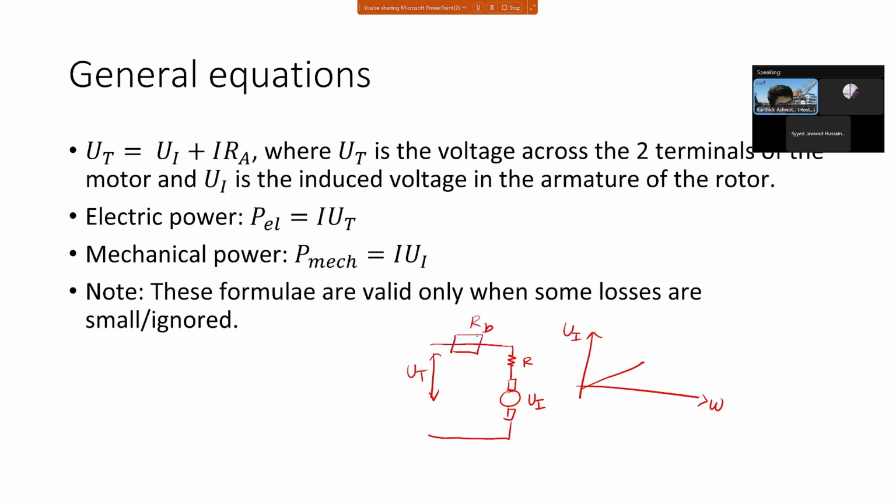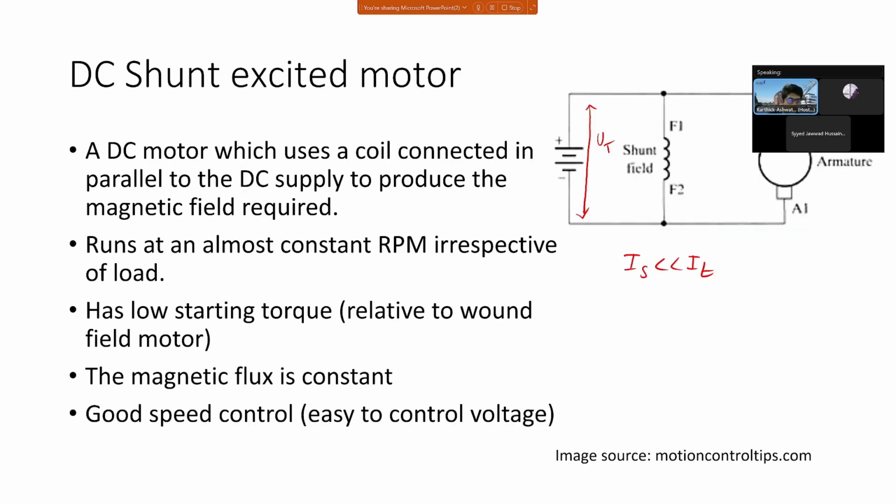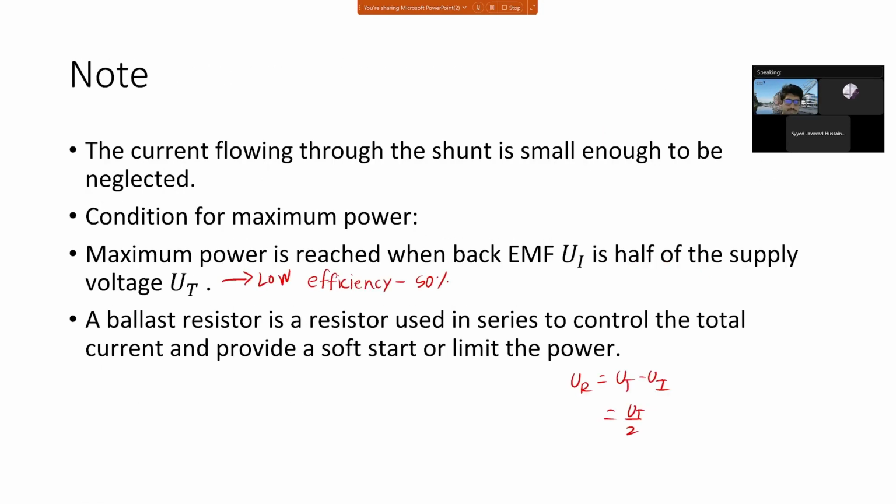It's called R ballast, and this resistor controls how much it decreases the amount of current flowing. Once the armature has started spinning a bit, we then disconnect this ballast and make a connection across it, so that there is full current flowing, and then the current surge is avoided, and it gives this soft start feature so that there is no sudden increase in torque.